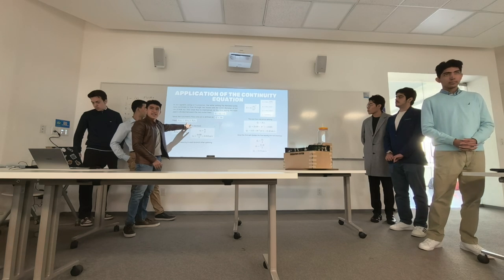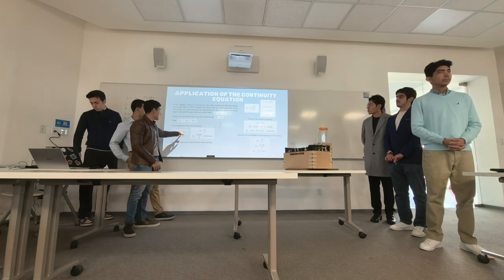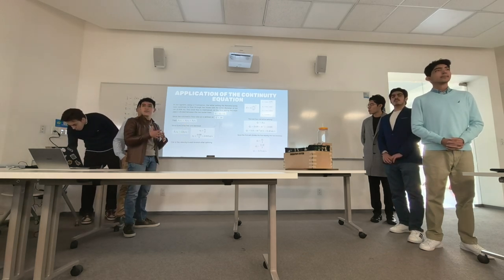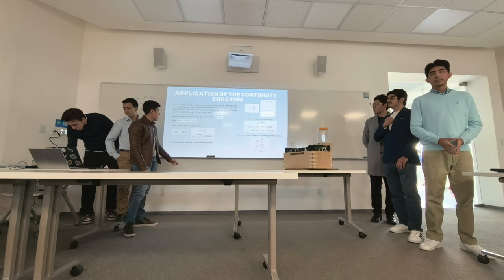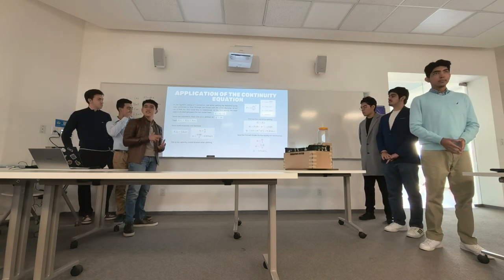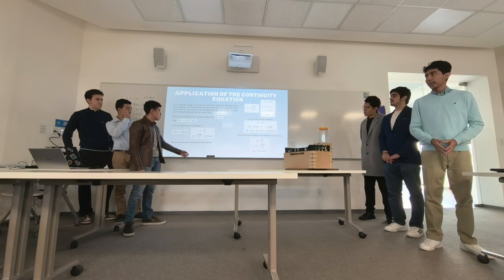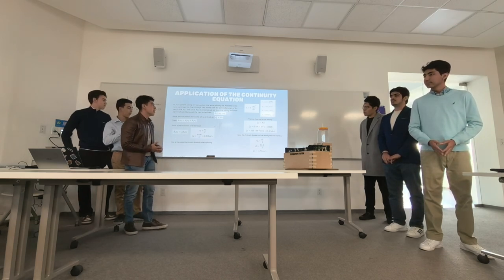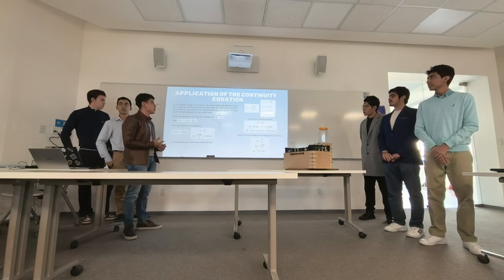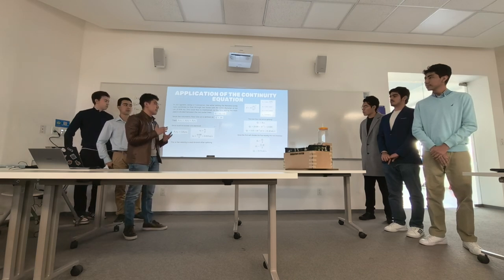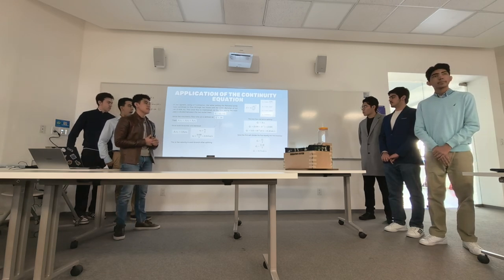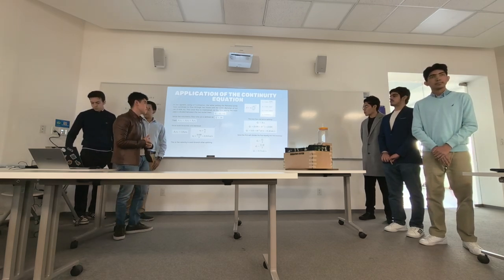But as they are identical, we can say that this area times velocity is the same, so we multiply them too, as it's the same. Then, for obtaining the next velocity, we simply divide the initial velocity by 2. And the result was 0.3 meters per second. We also calculate the total flow rate, multiplying the area times the initial velocity. And as it also splits, it divides into 2. The result is 15.74 milliliters per second.